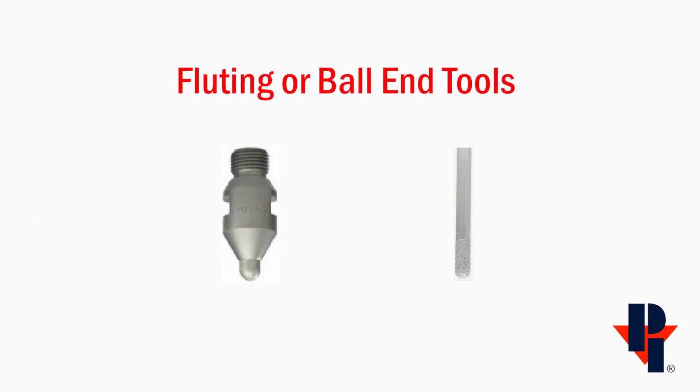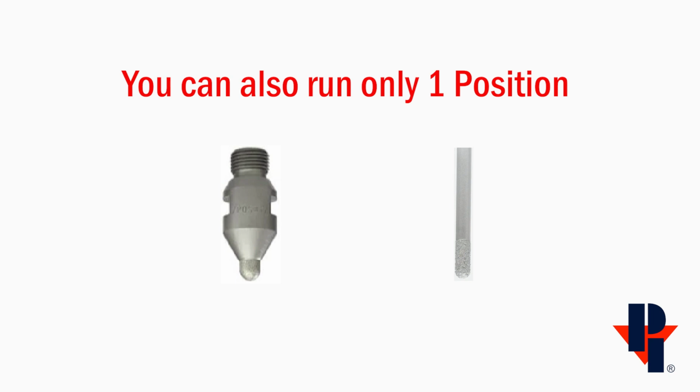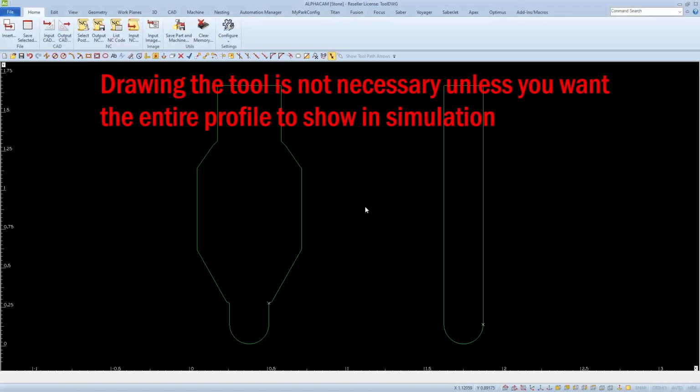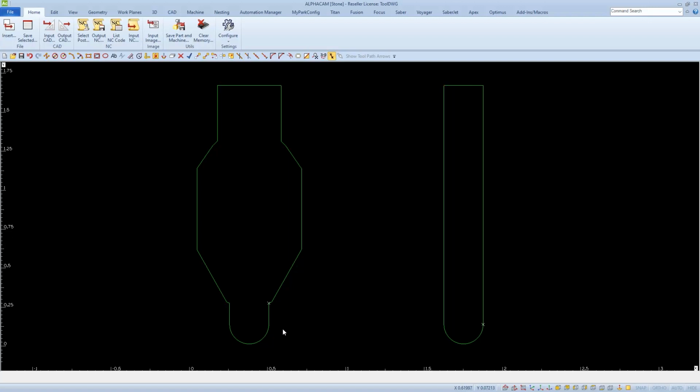The tools typically used are called fluting tools or sometimes a ball end mill, and they may be purchased as a set of 4, or you may choose to only run one and then hand finish the flute after it's cut. These tools will need to be added to your AlphaCam tool library. You can draw them and add them in as a user-defined tool, but really, the only part of the tool that will be used in fluting the drainboard is the bottom round tip.